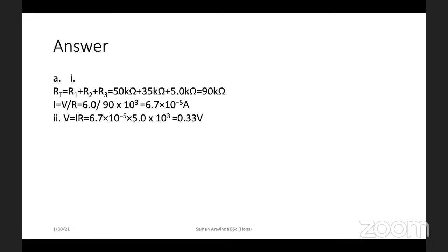So the voltmeter is not connected across the LDR. It is connected across the fixed resistor. So light intensity increases means the resistance across the LDR reduces. So that reduces the potential difference. However, all these potential differences add up to 6 volts. That means across the other two, it should increase to compensate for the reduction. All right, so let's write this answer properly.